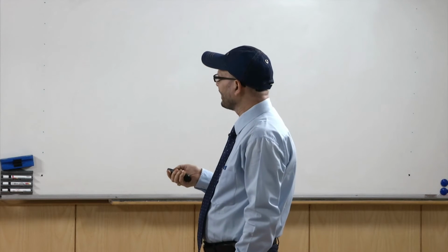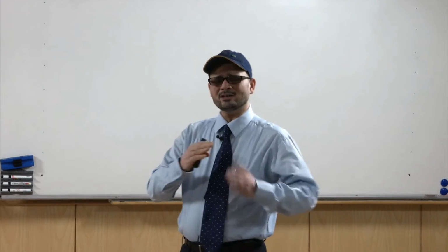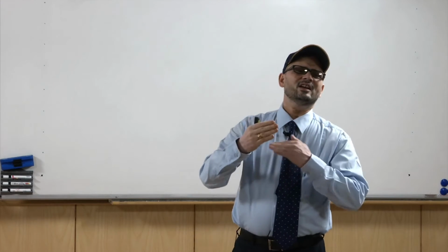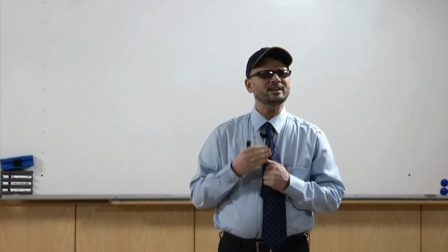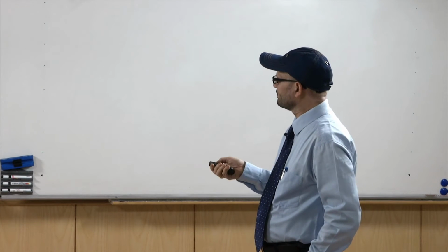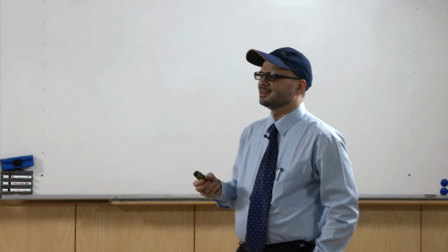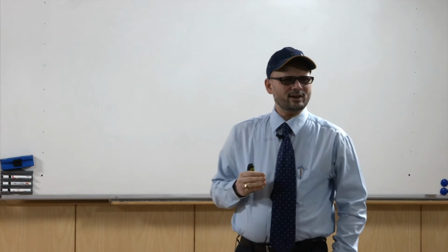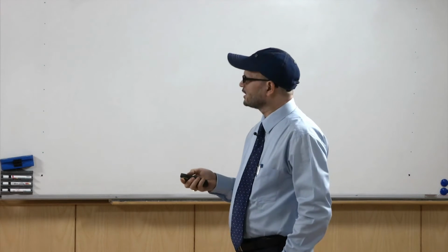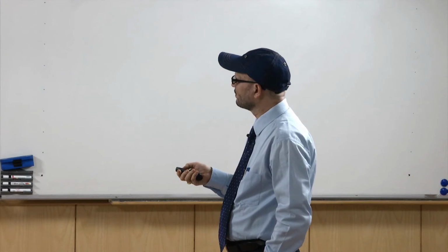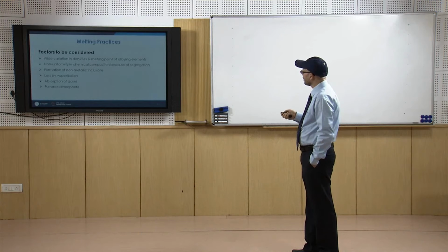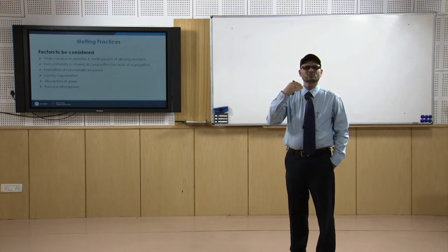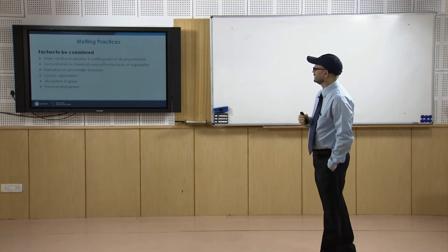Then the melting points also vary, and if the melting points vary, there may be associated problems related to melting. Many times one element melts while the other is already in the volatile state. So, these are the challenges in the case of these non-ferrous materials, and there are remedies for that which we will discuss. Maybe you can use master alloys in such cases.